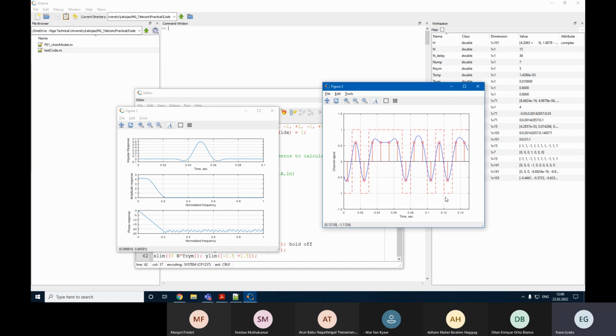And one last thing I'd like to show you, what happens if this phase frequency response is not linear. There is no way I can do this with this filter. I need different filter that will not be symmetric. Yes, so for that reason I am going to actually calculate infinite impulse response filter and then convert it into the FIR. This way I will have nonlinear phase frequency response, and as a result you will see that signal will be distorted. Okay, so let's do this.